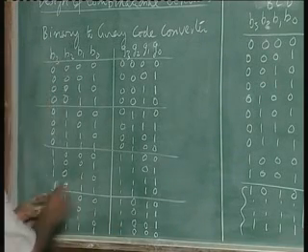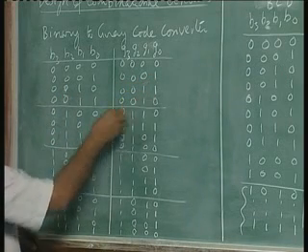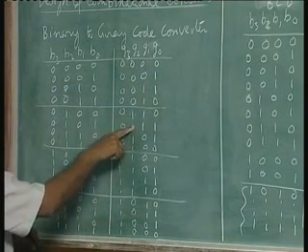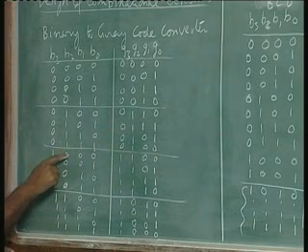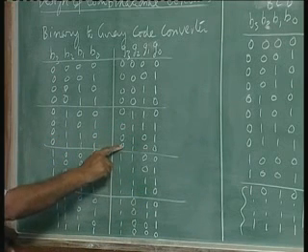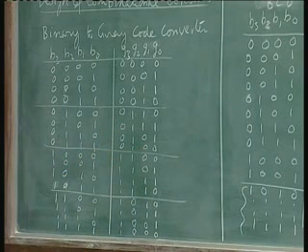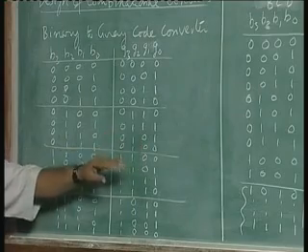You can see now between one number and the next number there is only one position that changes. For example, it is 7 to 8. 1, 1, 1 becomes 0, 0, 1, 0, 0. 4 changes. Whereas here is only 1. There is a 1 here. 0 became 1. Rest of them. Only one bit has changed from one number to the next number in a grey code.